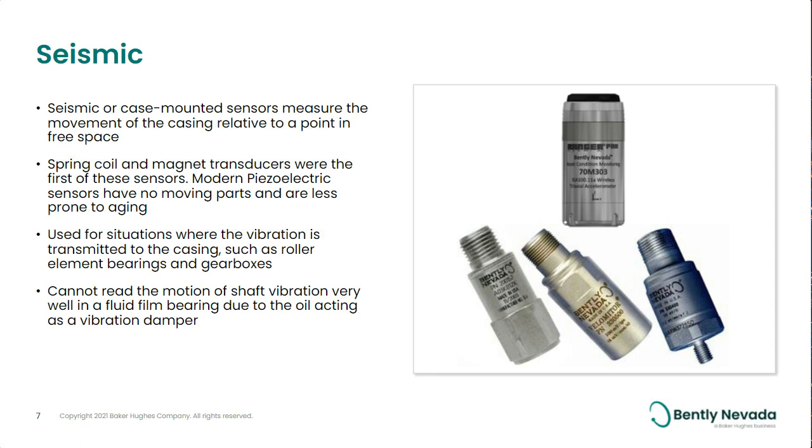Now, what I don't have on this slide that is very important for rolling element bearing diagnostics is that when you're doing diagnostics on rolling element bearings, you're probably going to use an accelerometer. Use velocity for protection, acceleration for diagnostics.